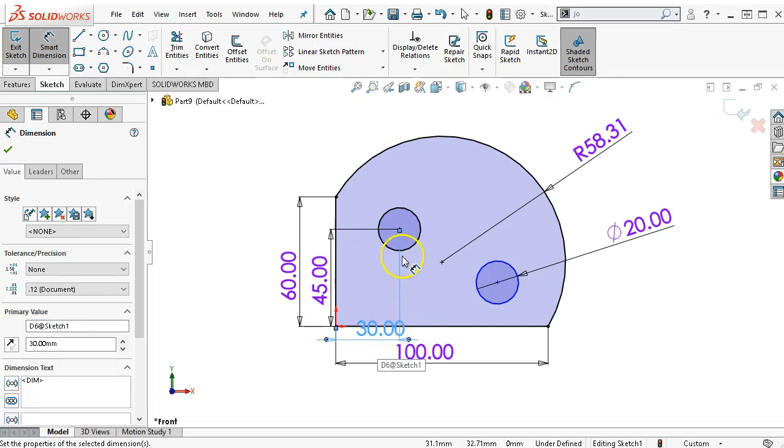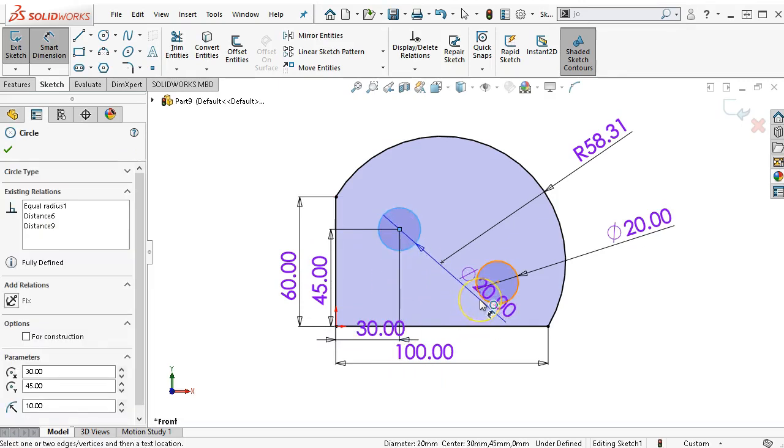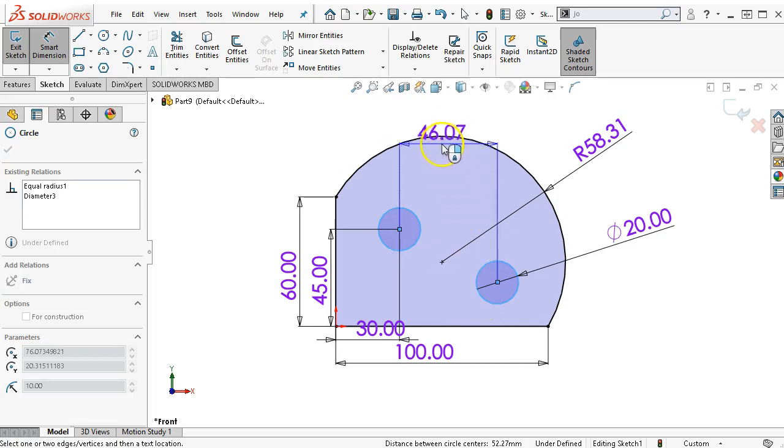All right, and then between the two circles, this is a definite watch out. This one comes with that warning of watch out for the center points. If I pick the two circles, I'm okay for going horizontal, vertical, and linear.